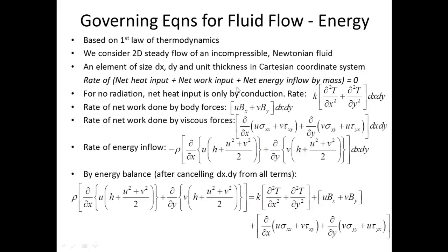The third governing equation that we are interested in is the energy conservation equation, which is based on the first law of thermodynamics. Subject to the assumptions that we have listed earlier, and considering a small fluid element of dimensions dx, dy and unit thickness in the z direction, we can write the energy conservation statement as follows: the rate of net heat input into the element plus net work input to the element plus the net energy inflow by mass into the element is 0.